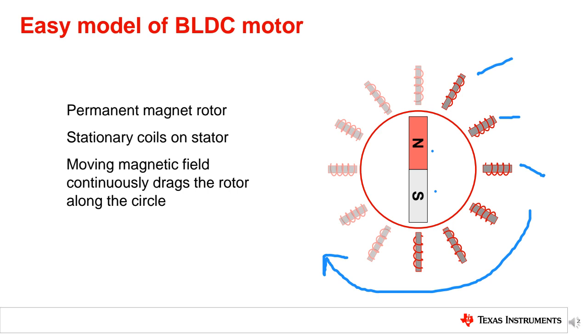This process of switching which coils have current injected to generate motion is called commutation. What is commutation? You can remember, in a DC motor, we have mechanical commutation. What is it? Brushes. In DC motor applications, we have brushes. In a brushless DC motor, we have no brushes, we have the electronic commutation principle. Okay, this is the main advantage of BLDC. It has an electronically commutated part.